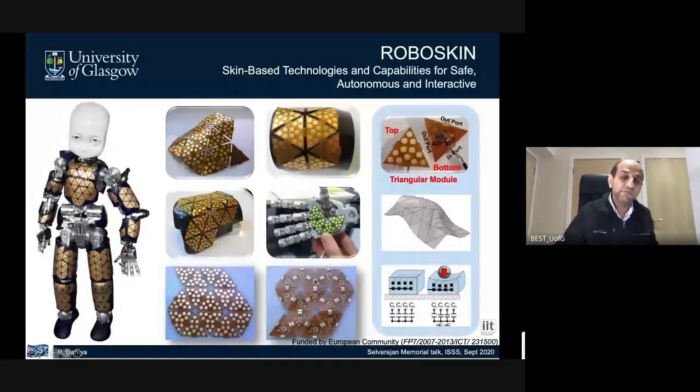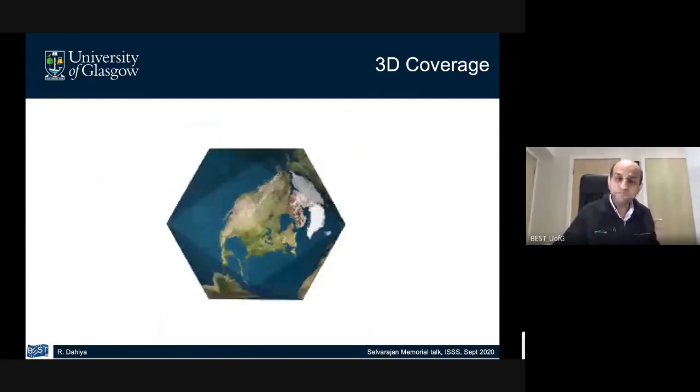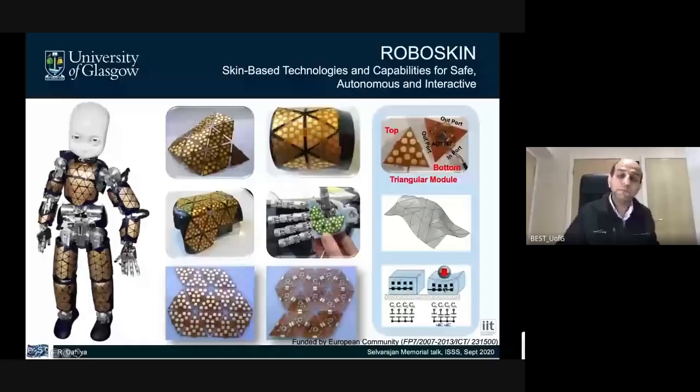On the back side, we have the chip, which is from Analog Devices, the AD7147. It's a capacitance to digital converter chip. So it converts 12 capacitive points into digital values. And on top of this, we covered it with a soft layer, and the soft layer was essentially a capacitive sensor. The top surface was a conductive fabric. It was grounded, and when you press the surface, the capacitance would change, and this change in capacitance is then detected as the amount of force and used to detect the contact point.